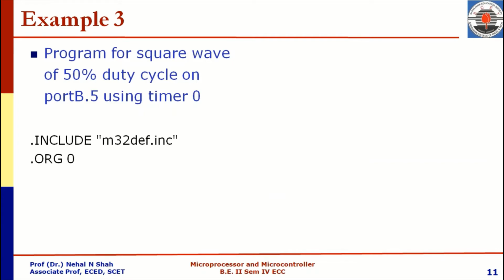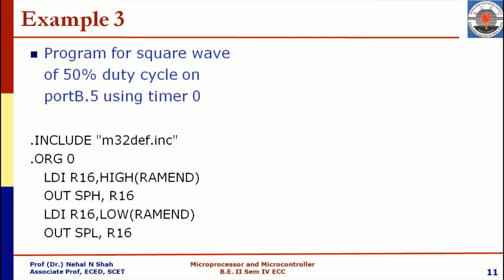So first of all, we will write our initialization from 0 location. We are going to call subroutine over here in this program. Due to that, we need to initialize stack pointer. To serve the purpose, SPH and SPL registers are loaded with the highest location of the RAM.